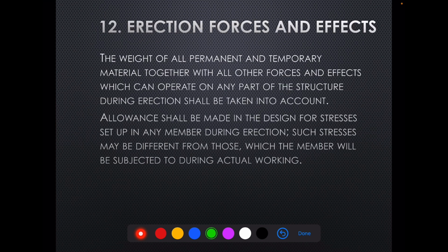The weight of all permanent and temporary material, together with all other forces and effects, which can operate on any part of the structure during erection, shall be taken into account. Allowances shall be made in the design for stresses set up in any member during erection. Such stresses may be different from those which the member will be subjected to during actual working.